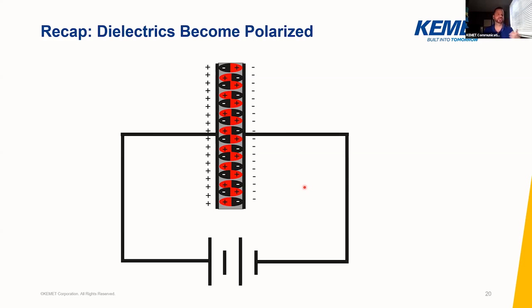All materials actually have that capability. The higher the capability is known as higher permittivity, which means that it has a higher tendency to polarize in the presence of an electric field. So everything does, even a vacuum. That's why you have the permittivity of free space. It's actually a very, very small number, but still it's there. And so does air. So if you have, let's say, this dielectric material here in the gray was air, this capacitor is going to have a certain amount of capacitance.